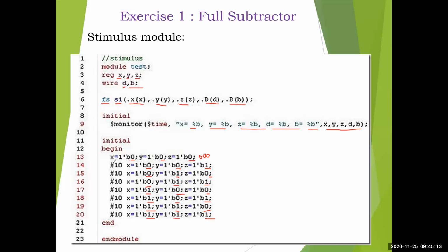So end, this initial begin. Since here initial has only one statement, begin and end is not written. See this observation here, initial is just written. If you have a single statement, there is no need to write it here. Multiple statements are there, that's why begin and end is necessary. Finally, end the stimulus module. So this is the program. Hope it is understood to you.